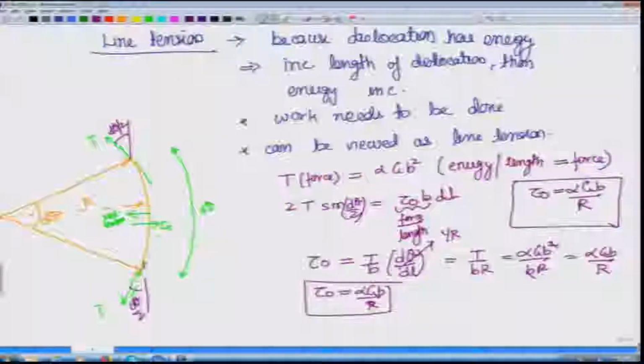The only unknown thing over here is alpha, and we know that from first order of approximation we can take alpha as equal to 1. It varies at the most between 0.5 to 1.5. So you will have error in that range only, but nevertheless you would have a relation which will describe how much stress has to be applied, or the converse, how much shear stress is being experienced by the dislocation, if we already know that it has some radius of curvature r.